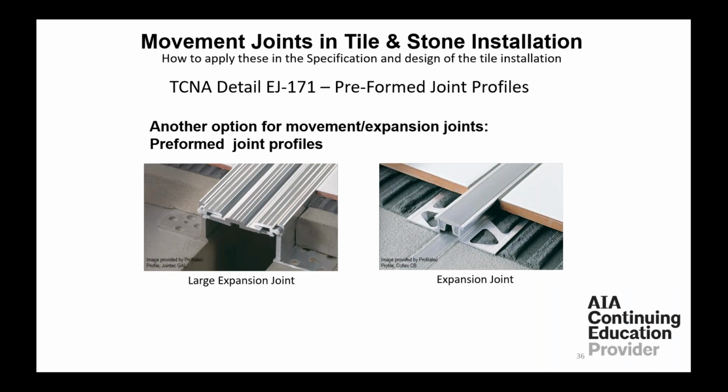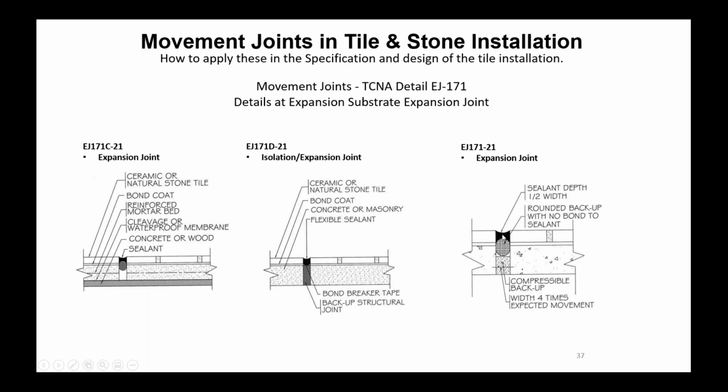Again, preformed profiles are another way to look at it. And I will tell you one thing about these profile pictures: I'm not a big fan. The one on the left is fine because that's mechanically anchored. The one on the right is done through mortar, and obviously you really have to make sure that you bed that leg that's in the mortar well, in other words, it should be covered with mortar well. Those are always done just for pictures. They are nice and graphic, but that's not how we want to see them installed.